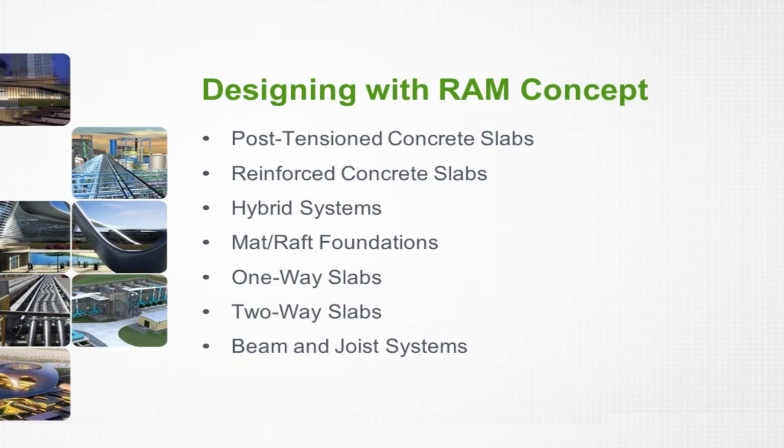Before we begin designing our mat foundations in RAM Concept, let's first discuss some of the benefits, or why you may use RAM Concept for your design. RAM Concept can design a wide range of structure types. This reduces the need to purchase and learn other products. RAM Concept can design post-tensioned, reinforced concrete, and hybrid systems for elevated and matt or raft foundations. They can design one-way slabs, two-way slabs, beams, and joist systems as well.